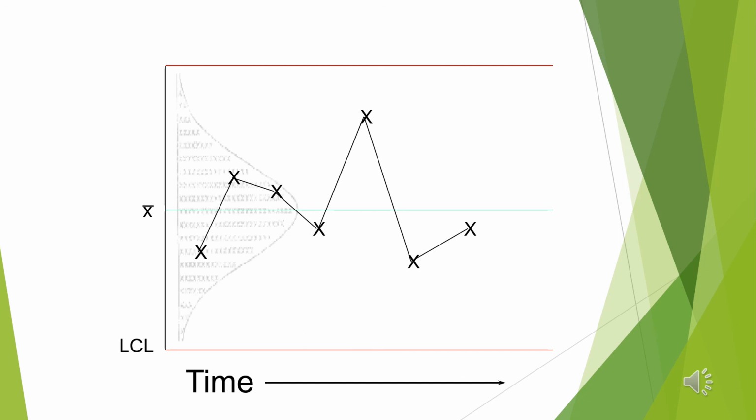Now watch this slide. I'm going to start off with my average, go up to my upper control limit, my lower control limit, have an element of time, right? And then I'm just going to start measuring points as I weigh the apples. Where do they lie in its weight? And I'm just going to go out. So it's the same thing as I did before, except I'm stretching it out over time. Now, if I were to take this thing after I get all done, tip it back over, all those little points will fall down and make that normal curve, a nice bell-shaped curve.